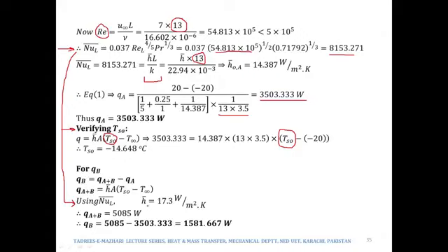so we will get some value of Nusselt number, and equating that average value of the Nusselt number to HL over K, we will get H as 17.3. So this H is in fact the average value over the 20 meter length, A and B combined.